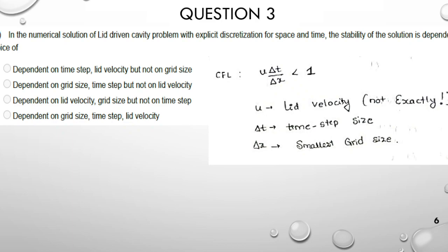Now usually what we do in our CFD codes, let me tell you that. We also do not go with the fully implicit as I explained it. Why? Because fully implicit, although I have personally written a code for it, takes too much computational time. So I usually go with semi-implicit pressure projection. It's not semi-explicit, it's semi-implicit, and semi-implicit pressure projection also has a stability problem.